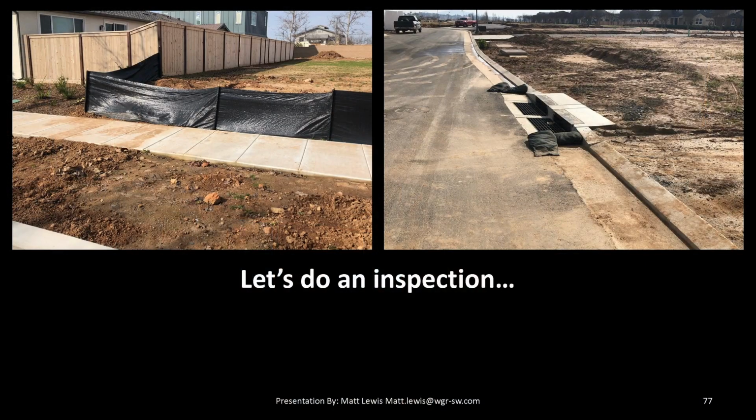And yep, the bags, at least they're trying. They got them installed fairly well. Although the whole L thing, I'm not a huge fan of the L because it kind of prevents that water from flowing around it, which you want to be able to get your water off site, and that tends to pool. But they're trying. But yeah, their curb cut back's a little bit of a mess.